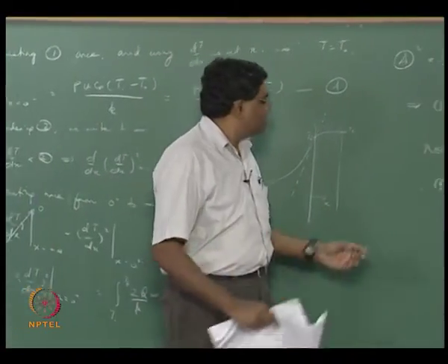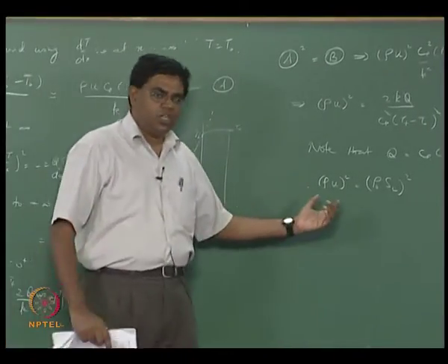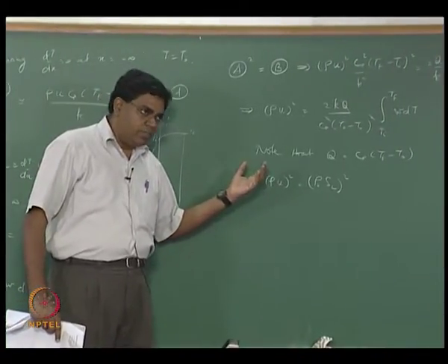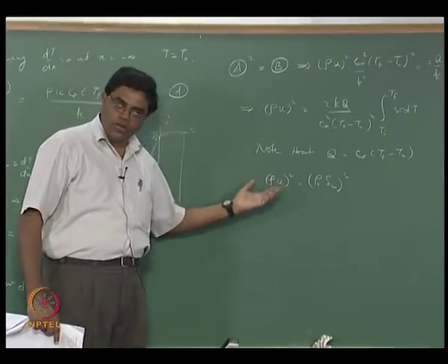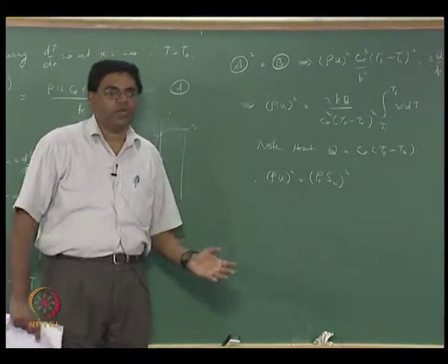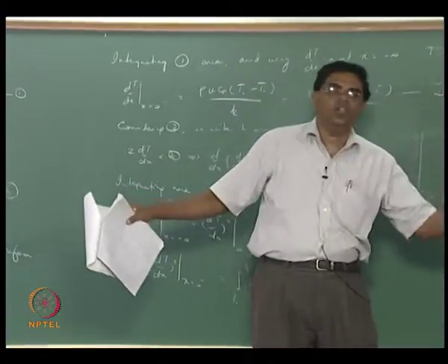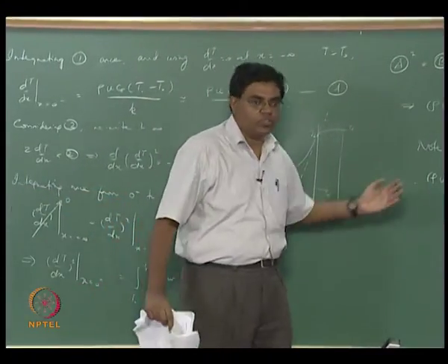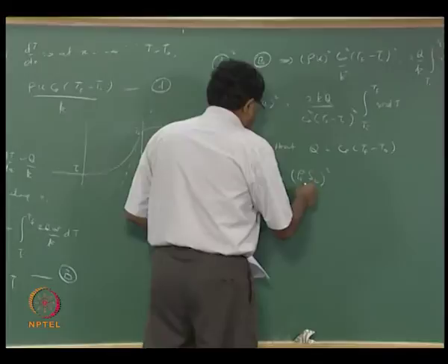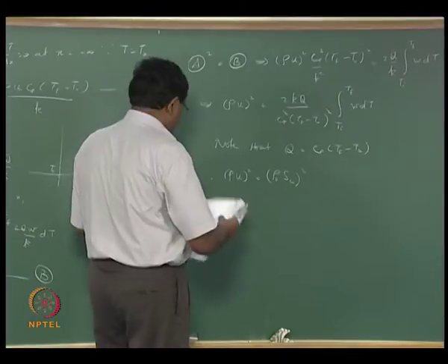Alright, but rho u is a constant, so a less controversial term is what's called the mass burning velocity. Okay, so mass burning velocity or mass burning flux, you can call it different ways, laminar mass burning flux is essentially rho u, and it doesn't matter whether you are talking about it with respect to unburnt reactant mixture or the burnt products, because rho u is going to be constant, you see. So when you're talking about a flame speed, then it has to be specified that we are talking about it with respect to unburnt reactants.